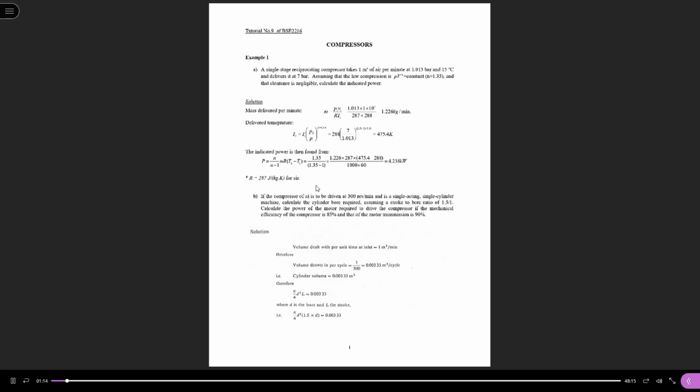So based on the types of compressors, we have reciprocating chiller and screw chiller. And we have to understand that reciprocating compressor chillers, and even our home air conditioners, are using reciprocating compressors. So it's suitable for small cooling capacity. Centrifugal chillers, with centrifugal compressors, are suitable for large-scale cooling capacity refrigeration systems.